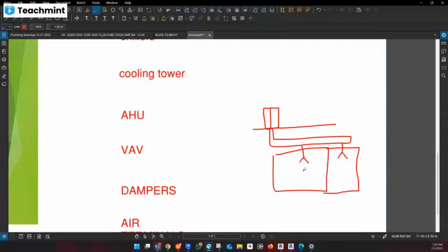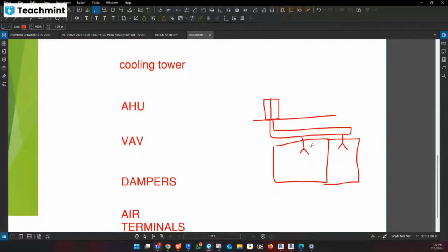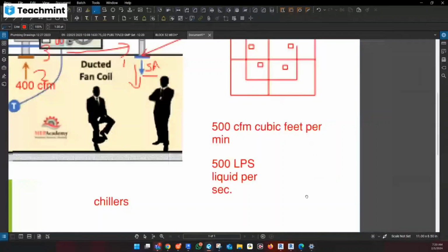Everyone is okay with this, right? It's a supply air. So the return air will be required to come back to this one. So we have to model a return duct also. That's probably, let's say, X CFM value. Return air is always equal to or less than the supply CFM. So it means the return air will come like this, come back here and connect with the machine again. That's called return air.